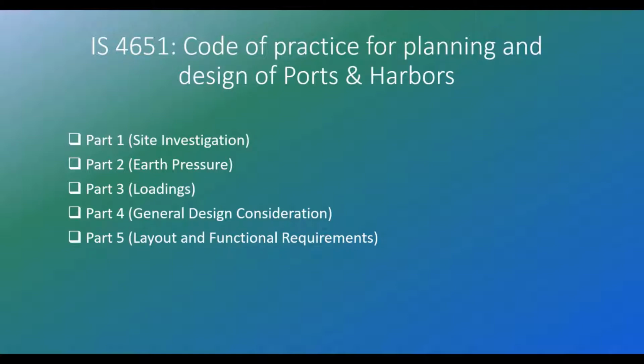Since port structures are complex in nature, earth pressure analysis is quite comprehensive. Hence, the committee has formulated a separate manual. Moving on to part 3, we have loadings. This section covers different vertical live loads and horizontal loads like cargo loads, crane loads, seismic, wind and berthing forces. Also, this code tabulates different vessel characteristics that are likely seen on Indian coast.